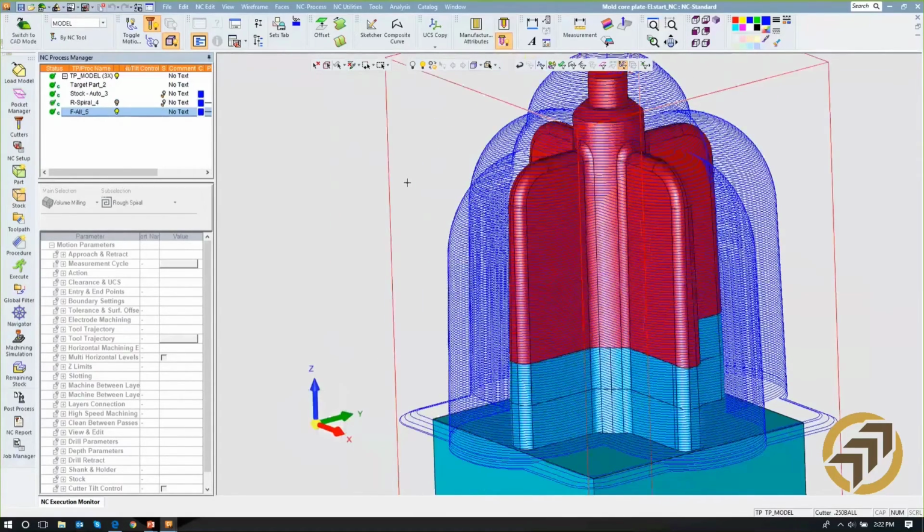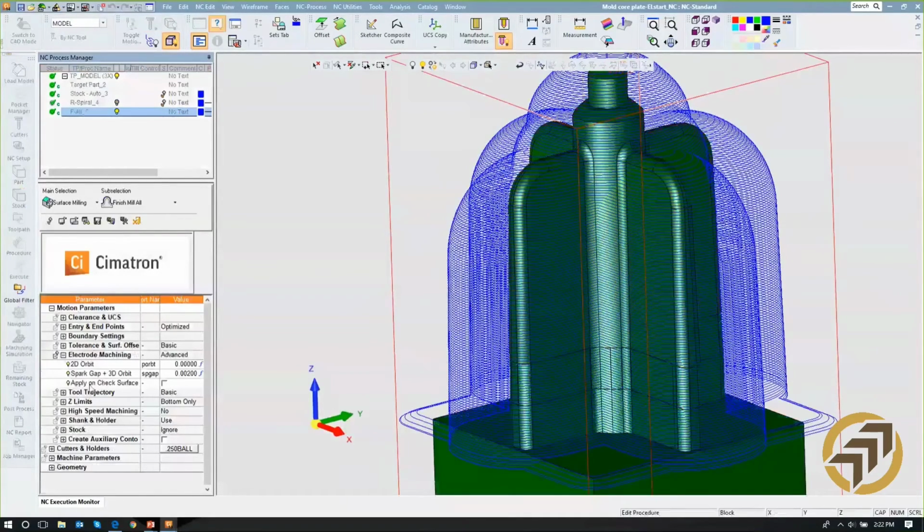Now, highlighting this one in particular, because here in the NC world, we've got the ability to program our cut based upon the orbit. So hopefully this diagram helps, it's a 2D orbit. It's keeping track of the fact that the electrode is going to go down to the steel and then move perhaps in a circular fashion, and it's the sides that are going to be affected. So it's the sides that need to have that gap. What this does then is it overcuts the electrode in the X and Y direction, but maintains it in the Z, which you can kind of see here in that little drawing.